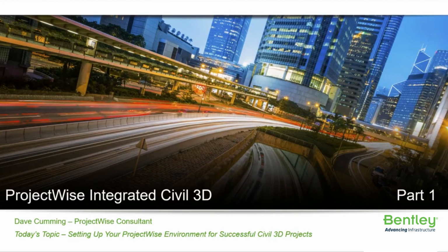Yeah, and the way I read the previous question about it was that I think the user was saying they needed 3.4 in order for it to work correctly. I would say that there's a chance, if you've been using Civil 3D for a while and you've got previous versions of the integration module out there, there's a little cleanup you might need to do on your end if you're getting fatal errors or something like that. I will include in this PowerPoint an appendix that will step you through that procedure. It'll involve reinstalling ProjectWise after you clean up some of the stuff in the places where it's keeping these modules. But that might be all that you're running into. I don't know of anything where it doesn't work correctly with the earlier versions.